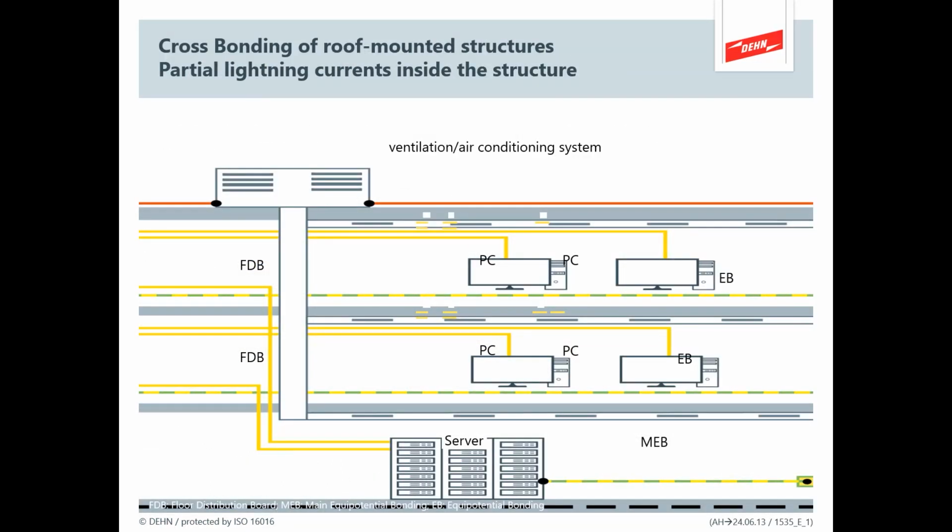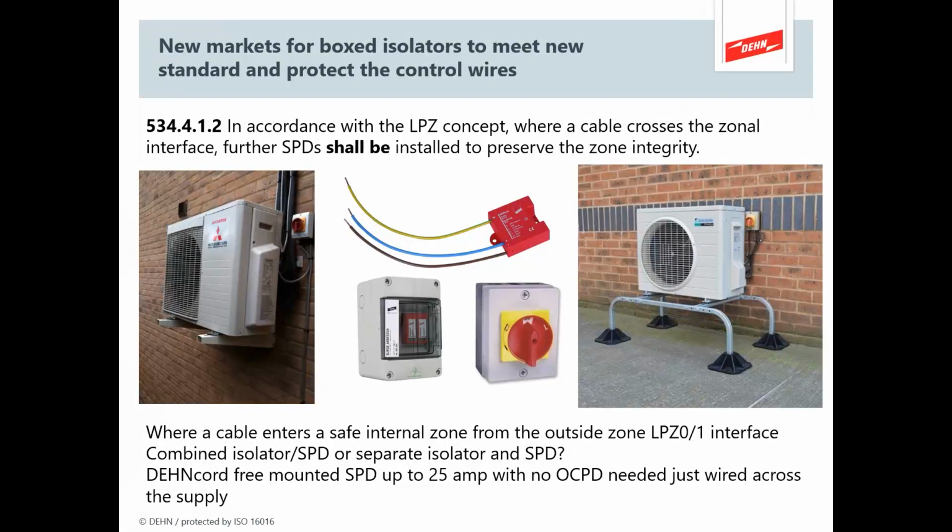And this is going to illustrate why we need type 1 SPDs. So lightning hits the plant on the roof because it's cross-bonded, and because there is continuous metallic ducting coming into the installation, the ducting which is providing the ventilation in the server room at the bottom, that all becomes energized, and any cabling associated with that ducting is going to have an influence because of those energies flowing within the metalwork. And that's why we need so many more of these SPDs in the data lines.